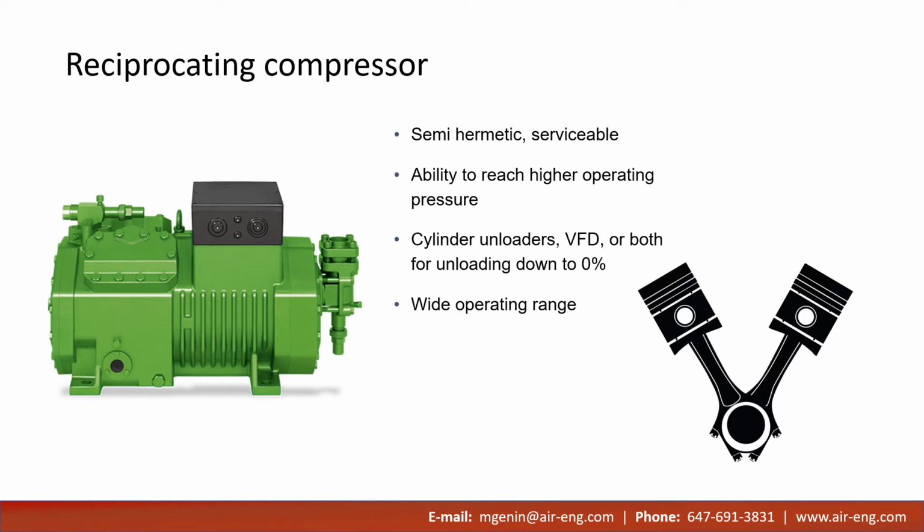Reciprocating compressors have been around for many years, and they have a very robust design. They have a solid cast iron body, which makes them suitable for extreme conditions, and a wide operating envelope. This is why they've been used for all kinds of applications, including low temperature applications and even high pressure applications that need heat recovery. The motor is located in this area, and it is cooled by the suction gas which enters this port here,